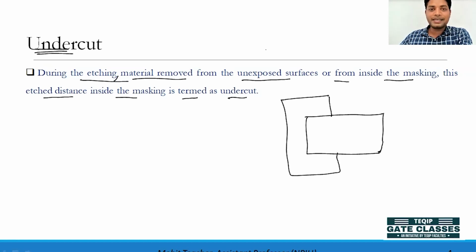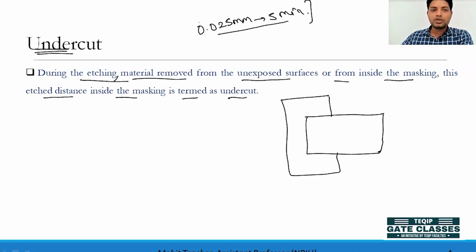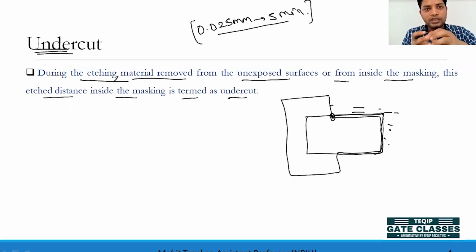Now first, as I said, if there is 0.025 mm removal of material in 5 minutes with the particular agent, what we are doing is, the liquid spills outside, because this complete surface is in contact with the chemical solution. So this will remove material throughout the area in contact. For example, if it is 0.025, then it will remove the material from this area. Now this area is clean, and after 5 minutes we bring it outside, shake it, and put it back.